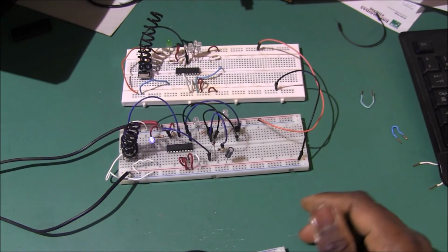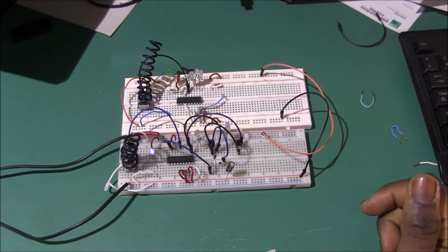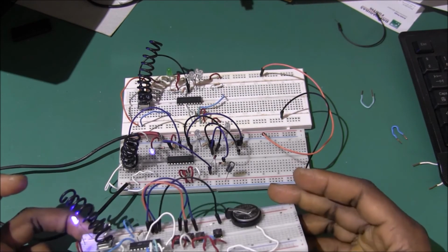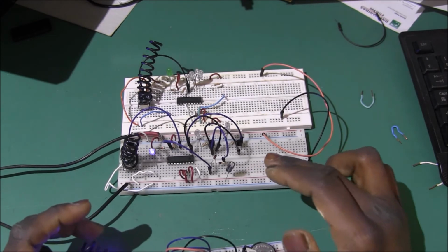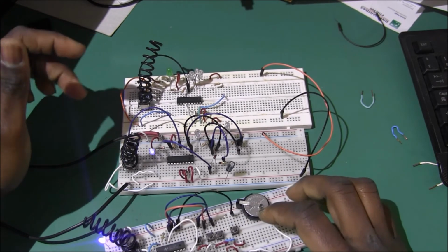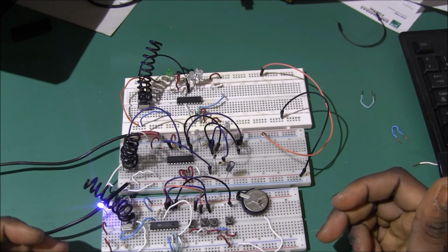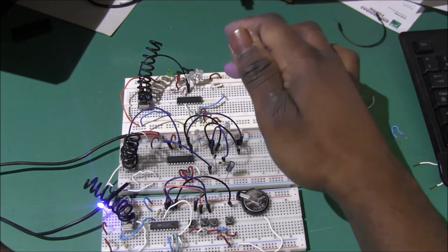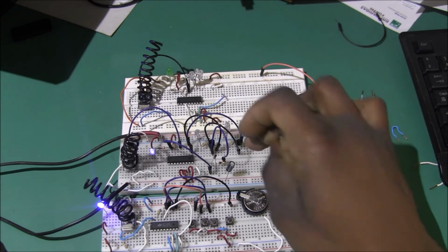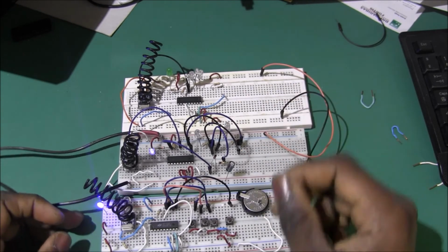The circuit I added is for safety purposes. For example, if you are switching something on and off, and you have gone out of range or the battery on your transmitter dies, this circuit ensures that the whole system stays off. We can see it here. If I disconnect the power over here, assuming the battery had finished or I've walked out of range, the outputs are going to stay on even though I'm not transmitting anything. So this is not a good setup. With the circuit I added, everything stays off when there's no signal. That's why the circuit is there.